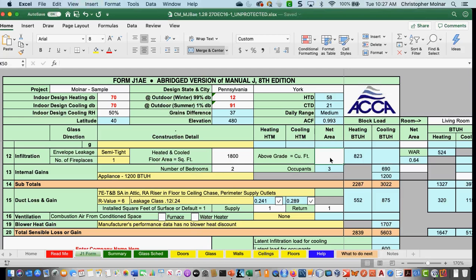If I have 1,800 square feet and I have 8-foot ceilings, how am I going to figure out my cubic feet? 1,800 square foot floor area times 8. Times 8. Okay, it's actually a relatively easy measurement. Now, if you have cathedral ceilings, I think somebody in here has mentioned you have cathedral ceilings, you have 2 choices. You can come close, or you could use math and figure out the area of that extra triangle.